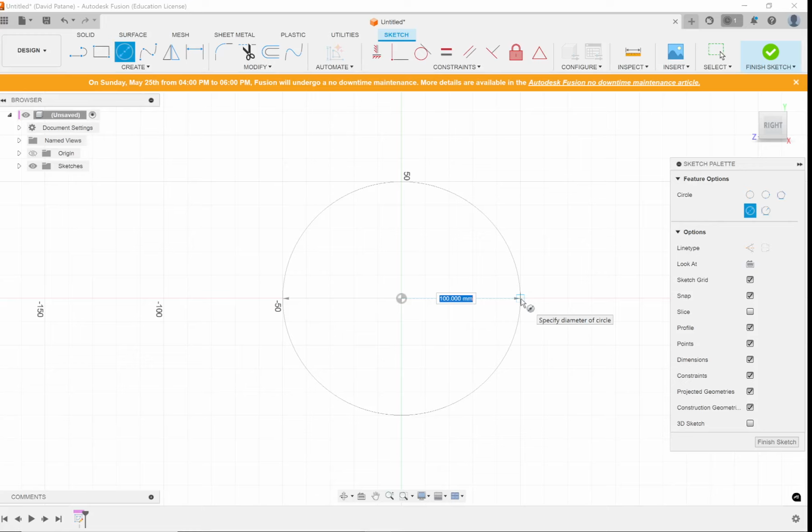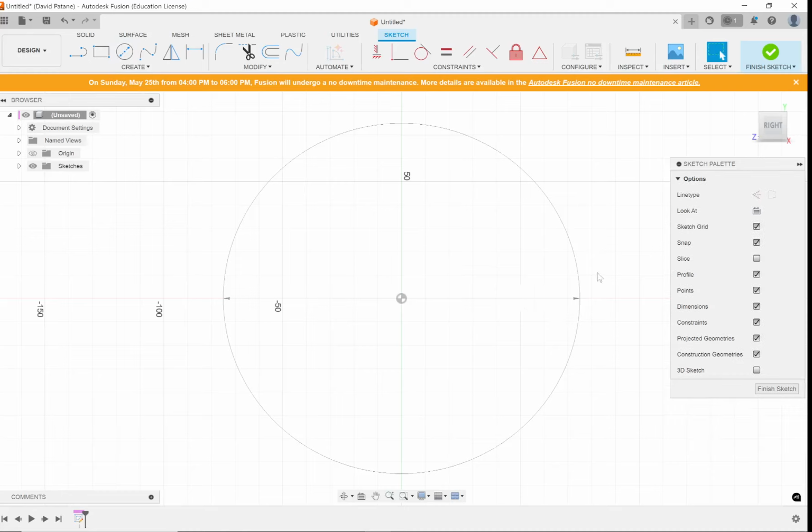So this disc brake, and I'm picking random numbers here, I want it to be 150. As you see, I can type the number 150 in here. One advantage of CAD, if I put in 150 there and I press enter, this circle is as close as my CAD software can make this circle to 150 millimeters diameter. It's assuming I've set this up in millimeters. Obviously, you can set up different sizes, and you can change the units.